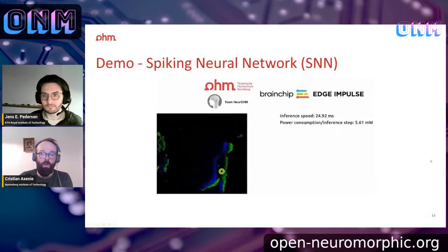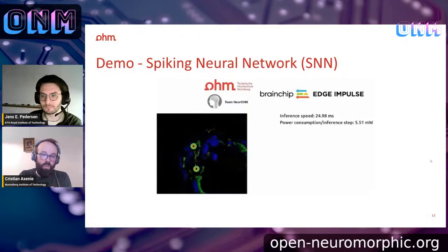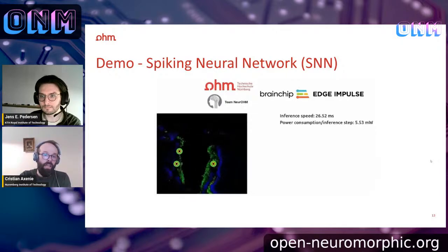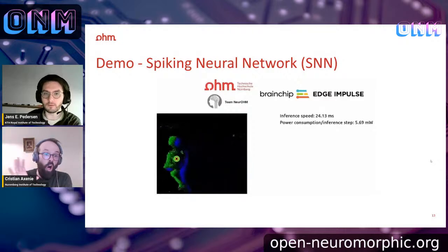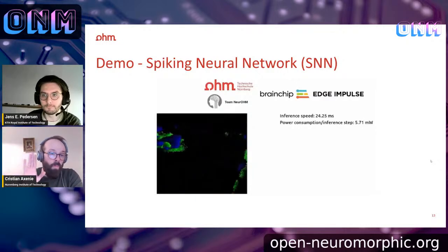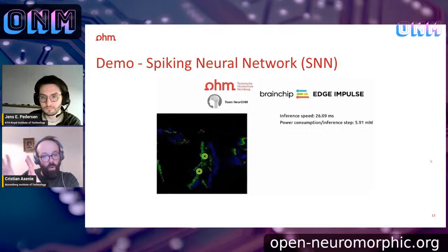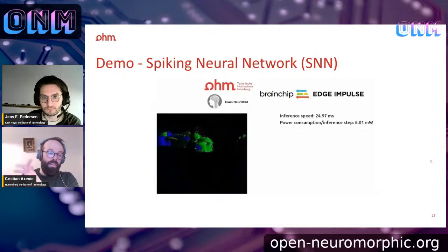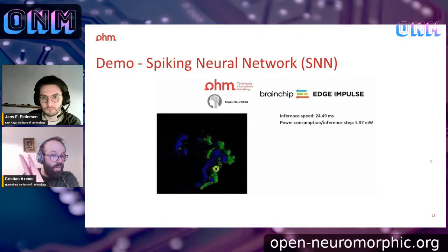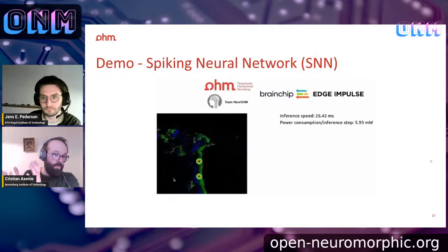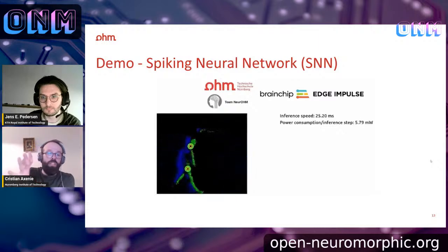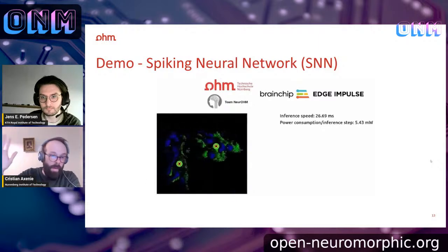So what we had was this. You see my slides, the power consumption per inference step. This was calculated on the BrainChip Akida board, without the Raspberry Pi platform. I don't have sensing data or current values from the BrainChip only. I gave you the power for the whole system, because this was important for us in the hackathon, to show how much it draws. Like 7 watts, it's fine.